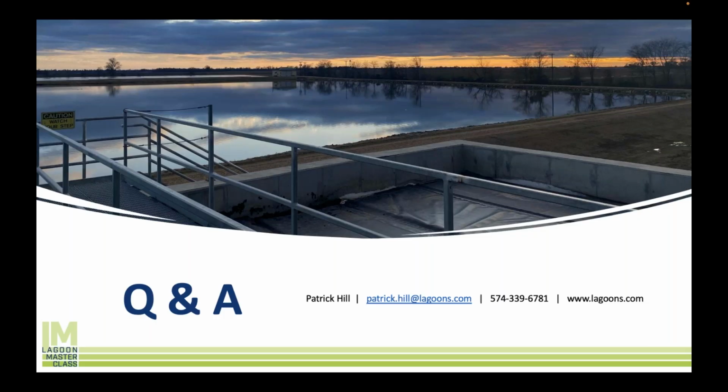You've got a particulate BOD sample that tells you you have a lot of algae, because most of your particulate is going to be algae itself. Then I would say, okay, that's a short-term acute problem. Now I've got to deal with that. And so I'm probably going to nuke it, right? I've got to go out there and use copper sulfate, right? To meet my permit today.